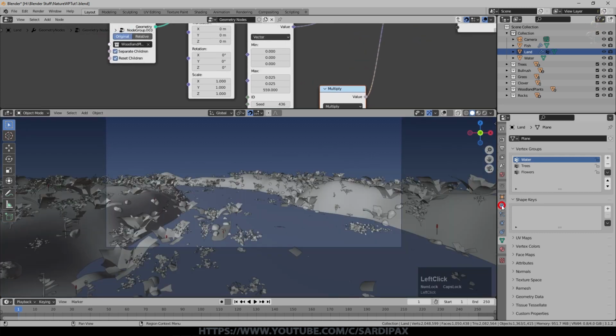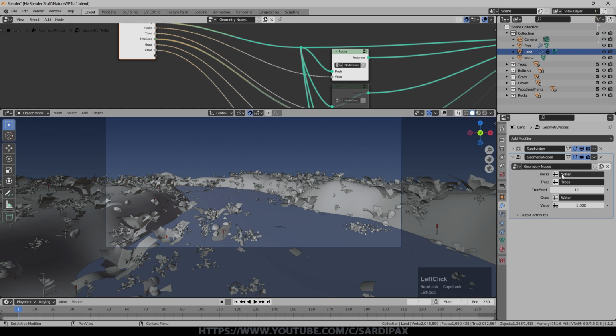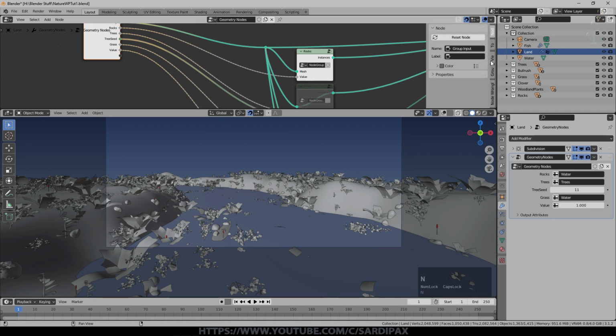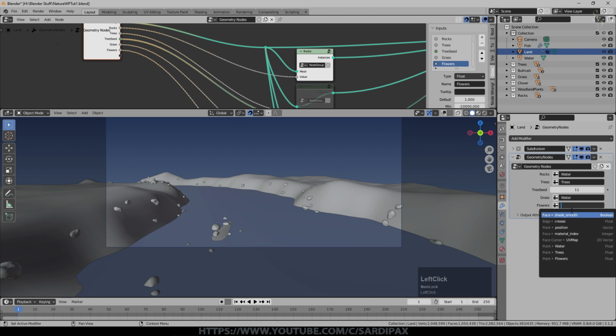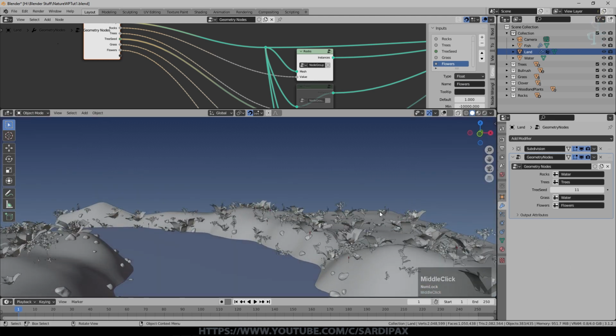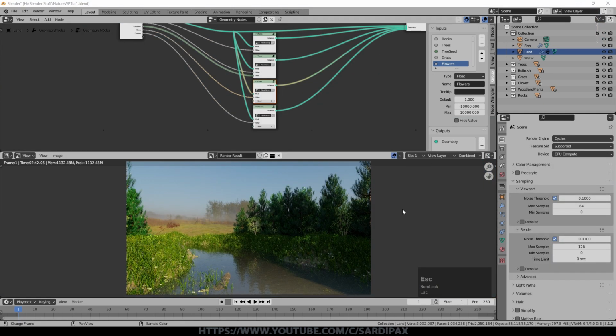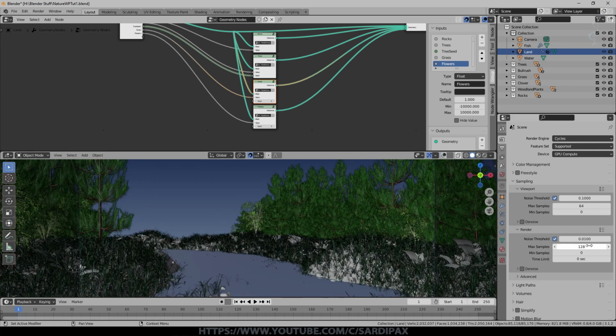But obviously we go to our geometry node, we need to do something with that. We need to set our vertex group. So I'll just give that a name and then click the little flag symbol and select flowers. I'm reasonably okay with the angles. So let's give that an actual render. So it's coming on. I think what I'll do, it took a little while to render that. So we'll bring this down now.